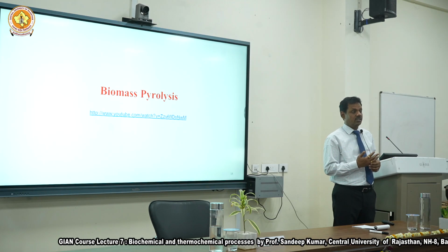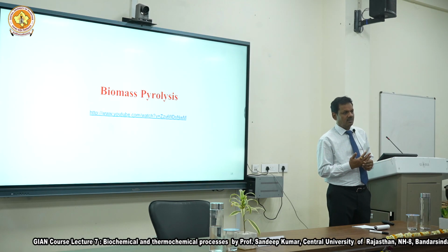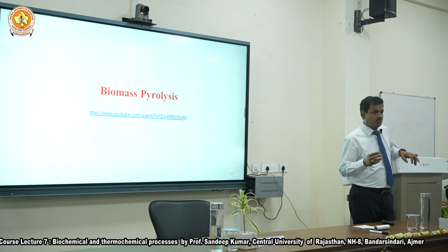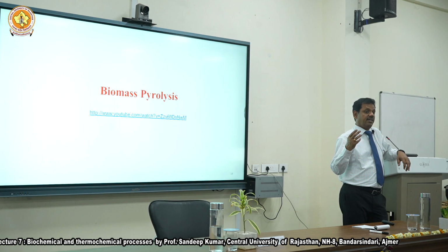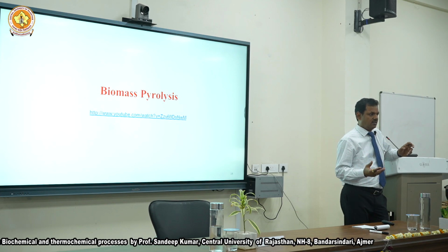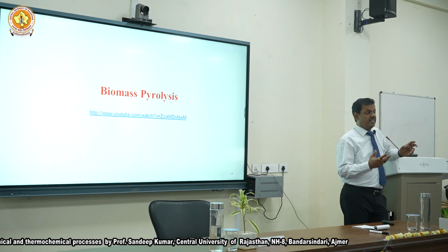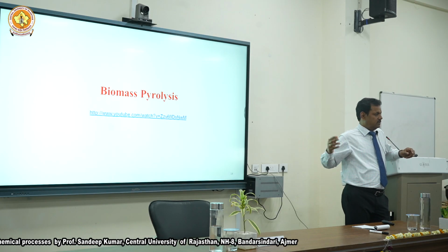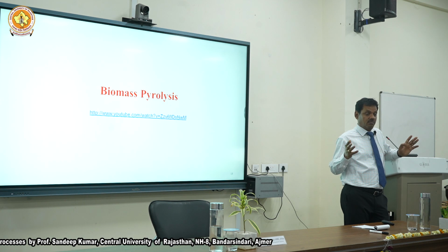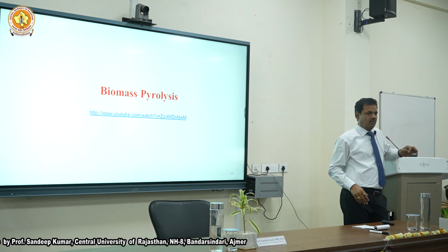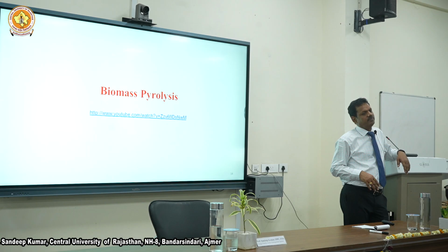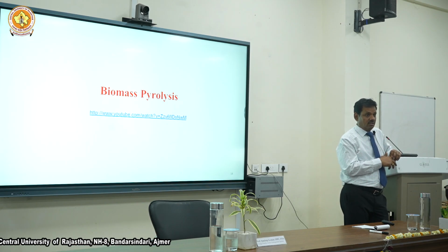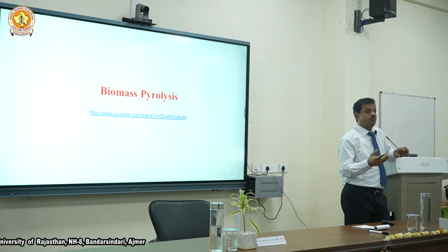So it depends on temperature and heating rate. So you get oil also. Now you have a system here where you can produce oil, you can produce gas, and you can produce charcoal. What do we need to produce? This is municipal solid waste and we are happy with some char to put in the ground and lawn, so we need more char. This is a fuel industry and we want to make diesel or gasoline, so we need to tune it such that we get more oil.